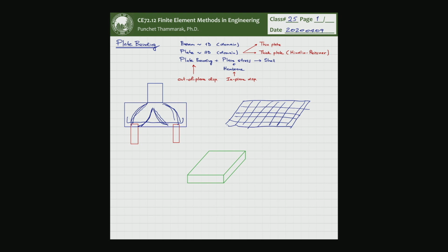So the use of the plate, in reality, is going to make your design conservative, because you design based on the theory of flexure, but the real behavior is in this strut mode rather than the flexure mode.